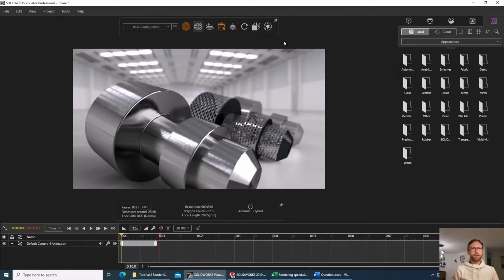But if you don't change the settings according to the denoiser activation, then it's not at all 10 times faster. It's exactly the same speed, or maybe even a bit slower. The reason that it is 10 times faster is that it needs much fewer render passes, and this results finally in 10 times faster. So we keep it activated.